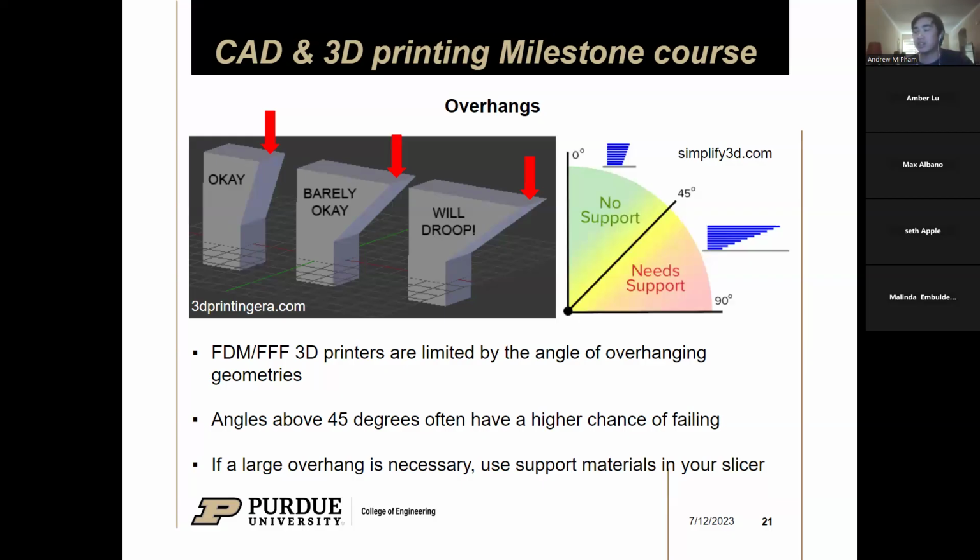Or it's a 45-degree angle, or at least the standard chamfer is. So if you chamfer something at a certain orientation that is just 45 degrees, it's not a steep overhang, and your printer should be able to reproduce it. So when designing your final, if you have an overhang, keep this in mind, because I really don't want to print supports because it takes more time and more material. And depending on your model, if it's really thin, then that support might break your model as you take the support off.